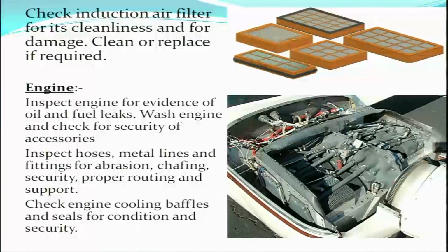Coming to engine, inspect engine for evidence of oil and fuel leaks. The very first thing to be inspected, your engine compartment should be free of oil leaks, fuel leaks. Wash engine and check for security of accessories. After that, we need to wash the engine and check the accessories are securely attached.